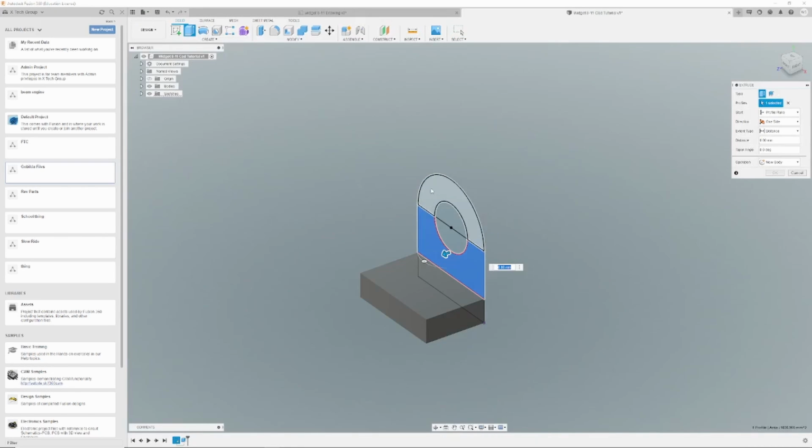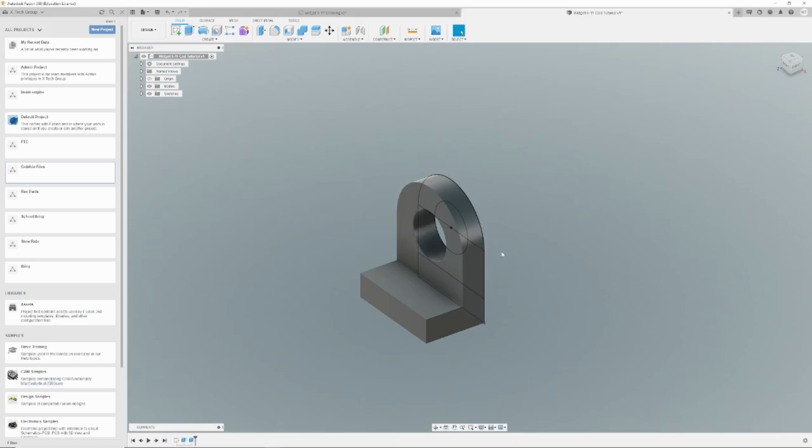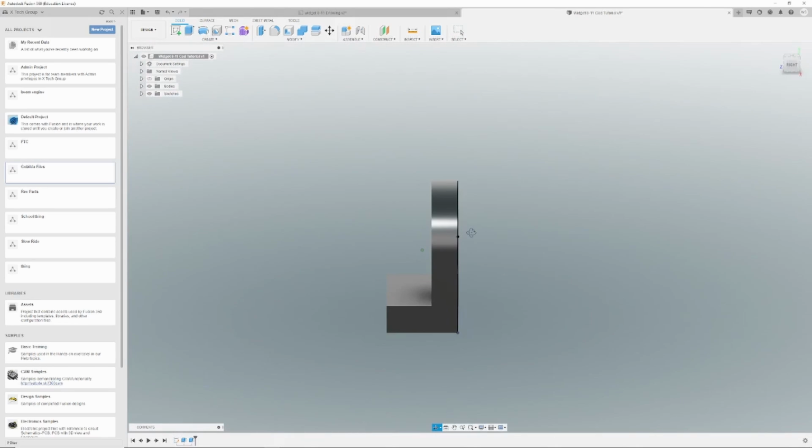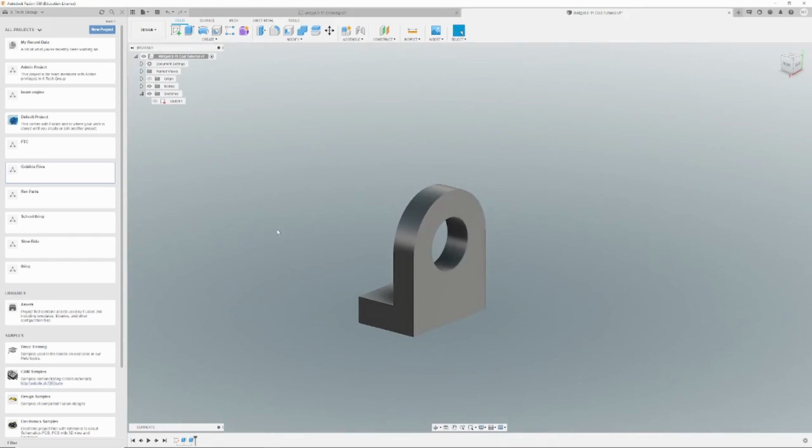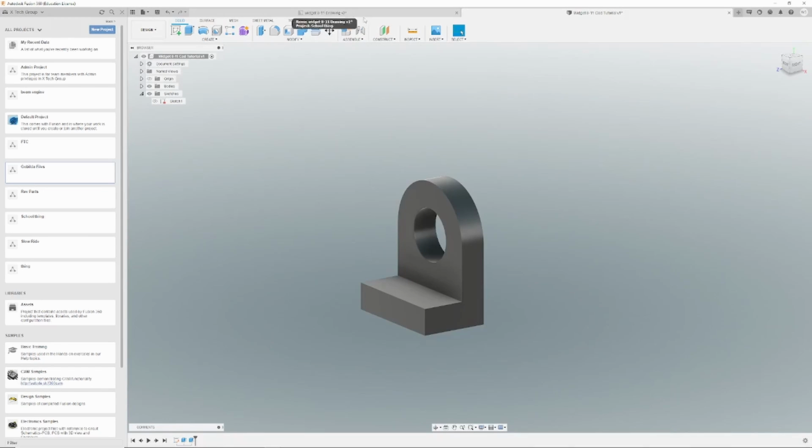So we'll extrude just these two sections right here, 11.7. Ooh, I got my math right. And now we don't need that sketch. So we'll come up here to this Sketches tab, expand it, and hide that sketch. And now we don't have that mess behind us.